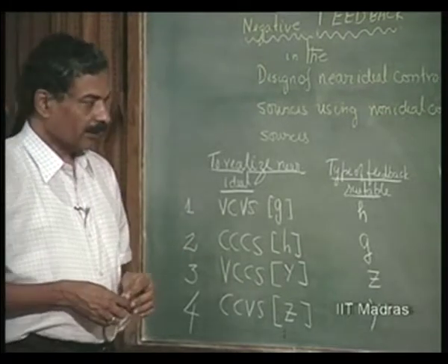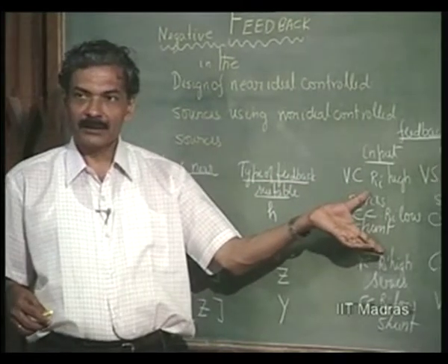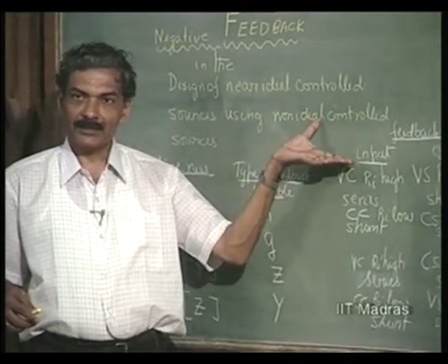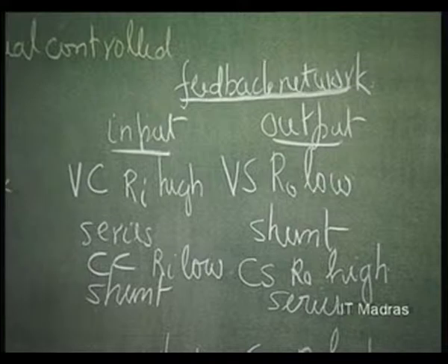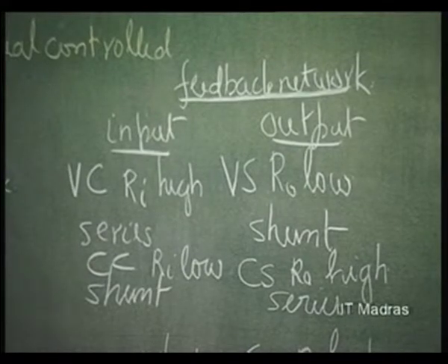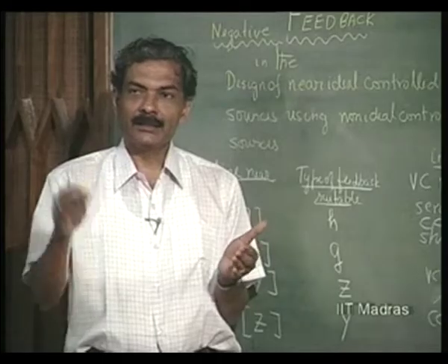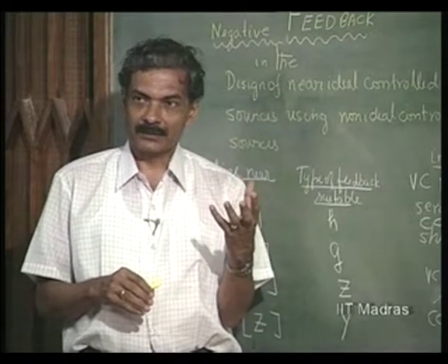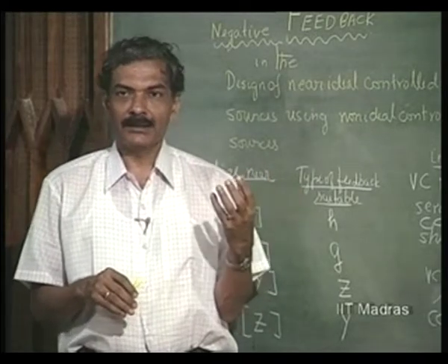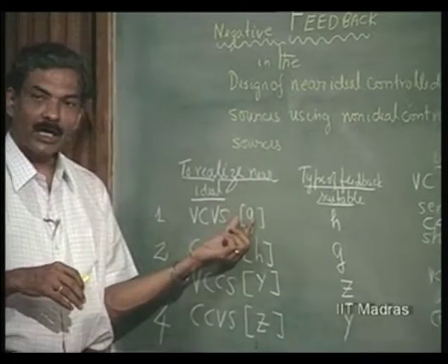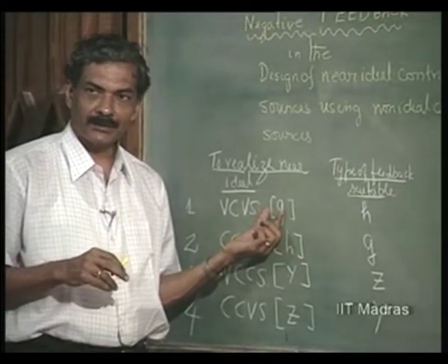Mathematically also we concluded H parameters add in this feedback arrangement: the H parameter of the amplifier gets added to the H parameter of the feedback network, and then if you have the H matrix, when you convert it into the G matrix, which is the inversion of the H matrix, you will see delta H coming and influencing every parameter. It is like loop gain; delta H is similar to loop gain. So, G I, for example, is going to be H naught divided by delta H.